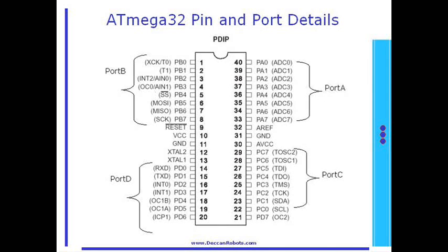Mega 32 is available in a 40-pin DIP package as well as in an SMD package. Your screen displays a DIP package version. Mega 32 has 4 ports of 8 bits each. In simple words, Mega 32 has 32 pins to connect input and output, grouped as 4 ports.